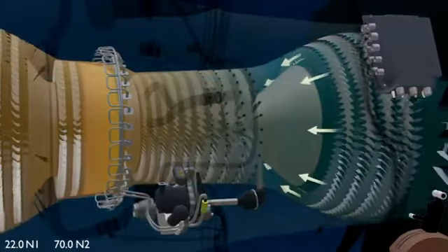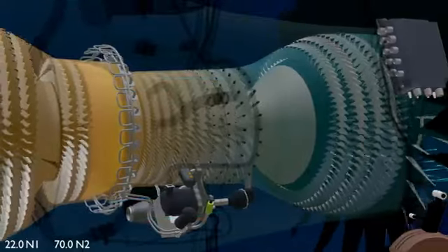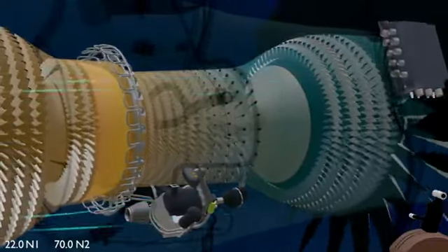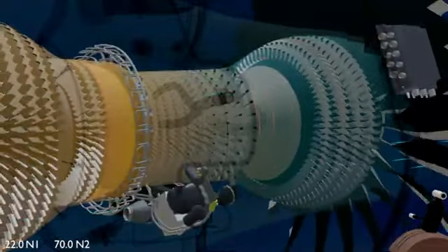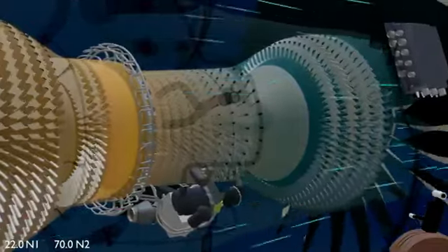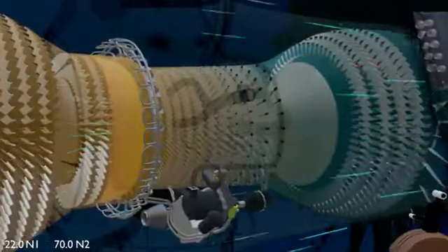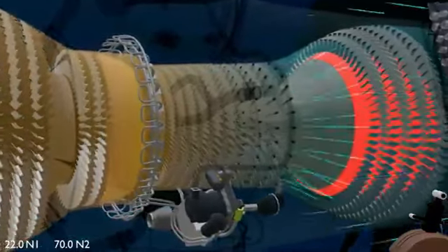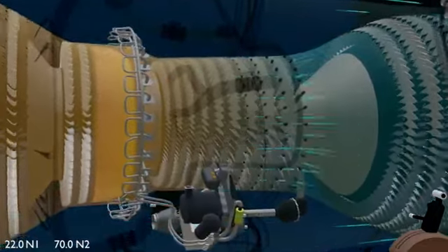When the engine is at low power setting, the amount of airflow that exits the low-pressure compressor stage is far greater than what the high-pressure compressor stage can handle. The HPC's inability to accept the excess airflow overloads the low-pressure compressor stages, which drops their efficiency and compromises the stall margin. If not rectified, the LPCs can experience a compressor stall and lead to abrupt engine failure. Recognizing this, the EEC commands the hydromechanical unit to operate the variable bleed system.